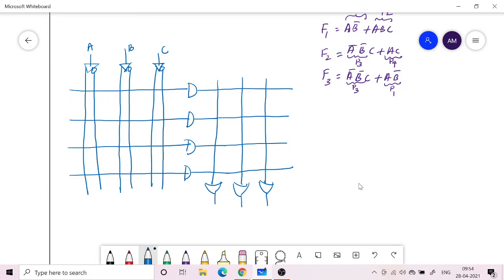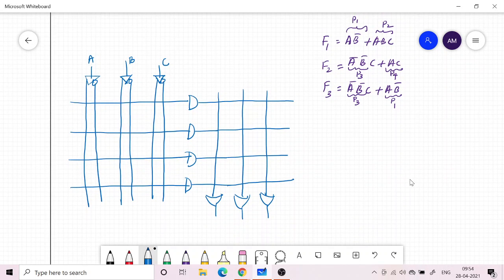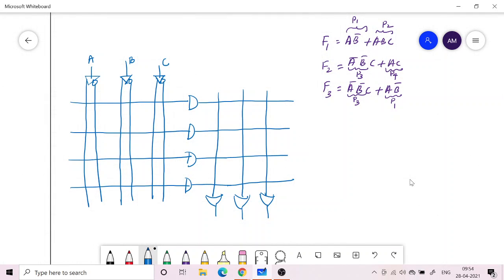Now you can program both arrays, the AND array input connections. You have the flexibility. For example, this AND gate has 3 inputs, so you can decide where each of those inputs is connected. And similarly, each OR gate can have 4 inputs, and where they have to be connected you can decide. You can see that this architecture is even smaller compared to the earlier architecture. First we started with 8 horizontal lines, then 6 horizontal lines. Now we have only 4 horizontal lines.